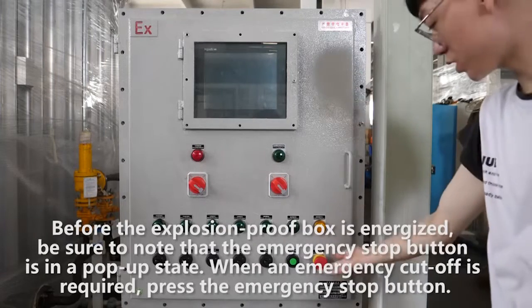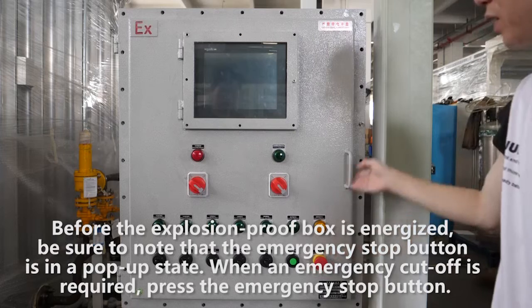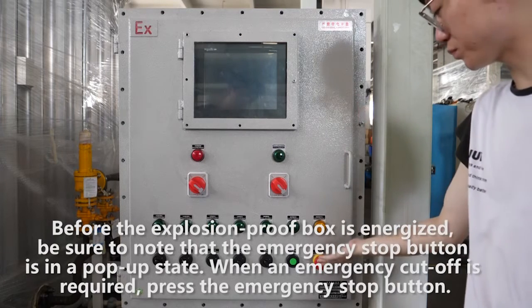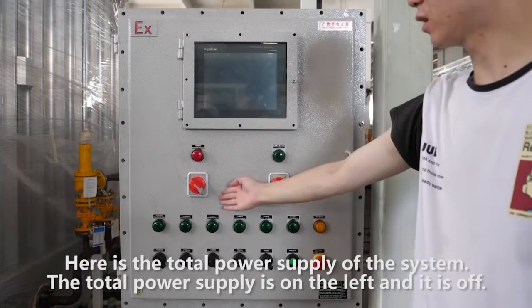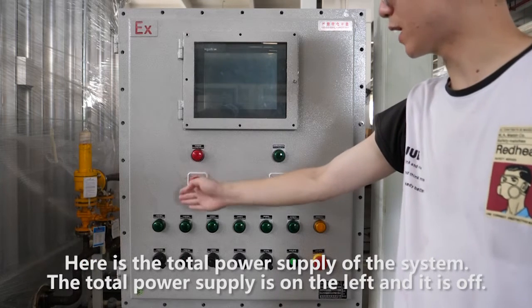Before the explosion-proof box is energized, be sure to note that the emergency stop button is in a pop-up state. When an emergency cutoff is required, press the emergency stop button. Here is the total power supply of the system. The total power supply is on the left and it is off.